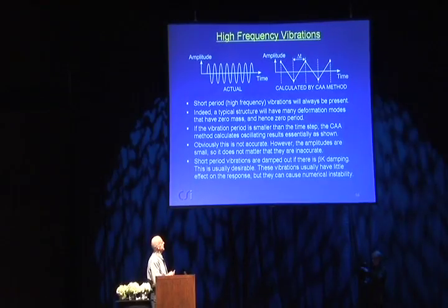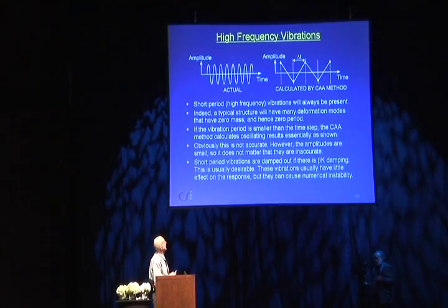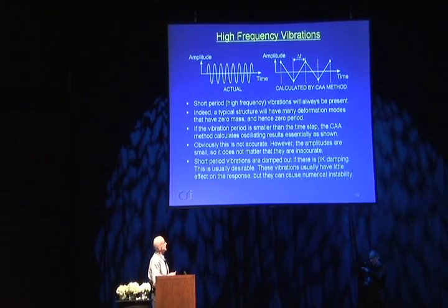The method still works. It'll still calculate a result, but it'll just calculate an oscillating set of results like this. And usually, with a controlled amplitude, the amplitude is often not too different than the proper one, but clearly this is not a very good approximation to this. So if the time step is long compared with the period of vibration of the structure, you're not going to get an accurate result. And in any particular mode, to get a reasonably accurate result, you need a time step of no more than 1/10 of the modal period.